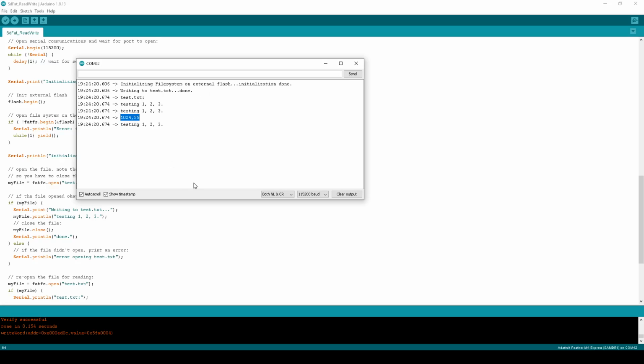What we've done is we went to the bootloader and copied the original code, the UF2 file. We uploaded CircuitPython to expose the USB flash. Once we exposed the USB flash, we changed one of the files and then wrote back the UF2 file. So this is one way to access the flash storage, modify it, and get back to the Arduino. It's pretty cool.